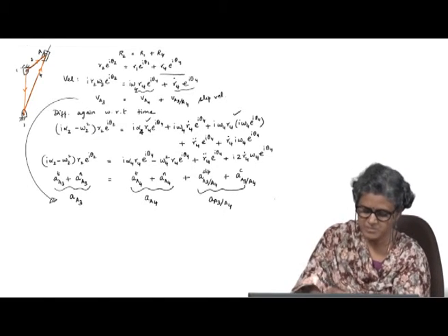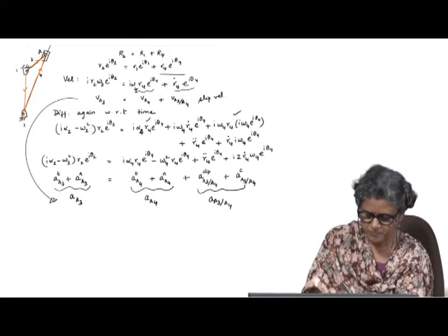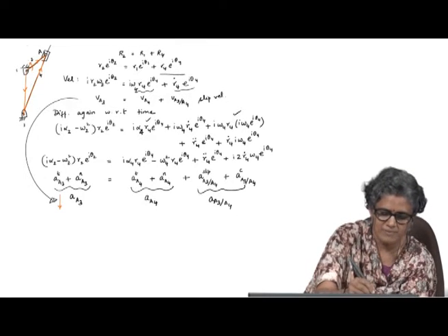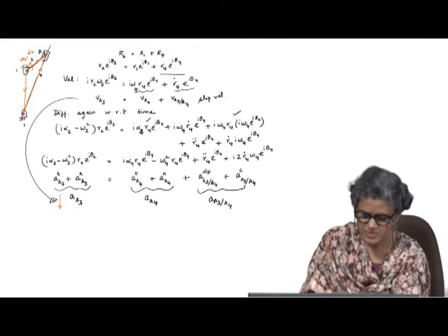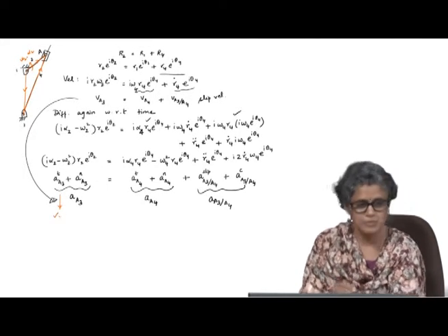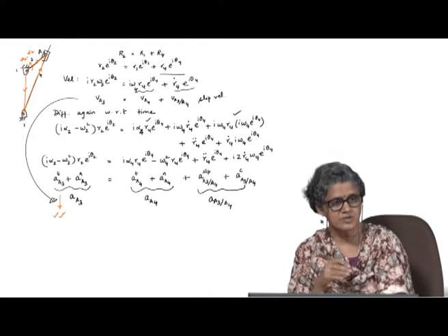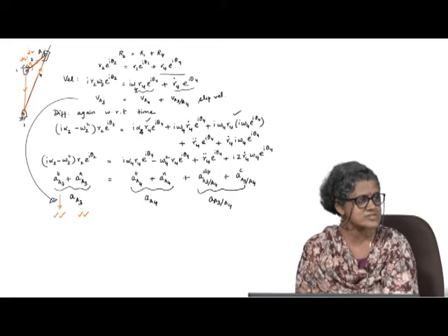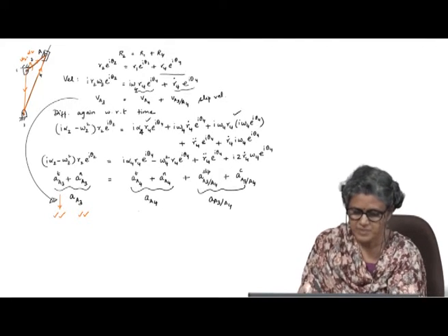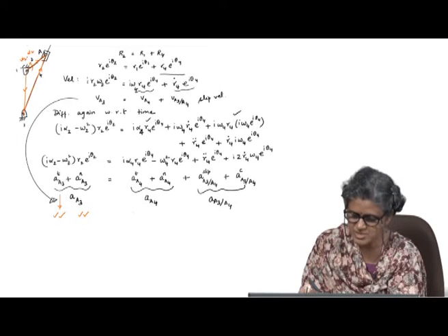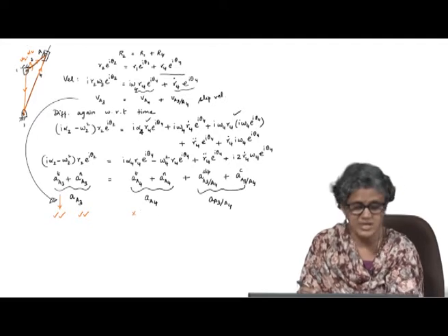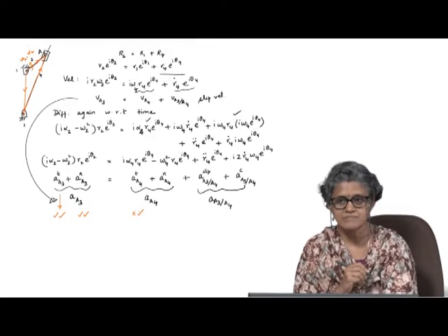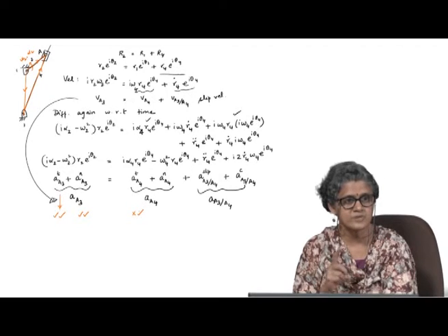So, if I look at this equation again, this term, if that is the input omega, I have omega 2 alpha 2 say. So, this is your input, so it is completely known. Direction is perpendicular to the link O to A. This one, again the normal component, is completely known from the velocity analysis. In the case of A on body 4, again the tangential component, I do not know the magnitude because I do not know alpha 4. Alpha 4 is not known, however, I know the direction. It is perpendicular to the link.